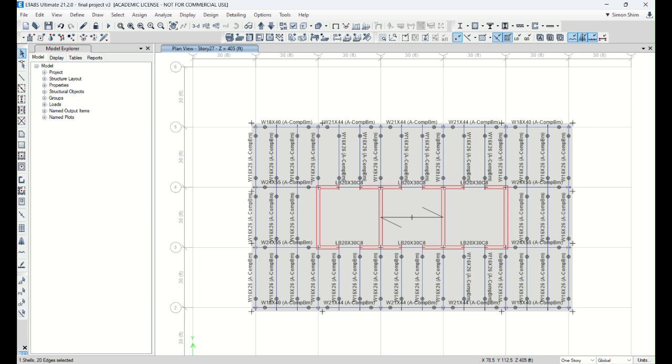You probably saw it downtown: there's a black building with huge girders around and very tiny windows. That is a moment frame. They don't have a core wall, so lacking a lateral system, they use the perimeter columns and beams as moment frames. That's why they end up with huge steel beams.